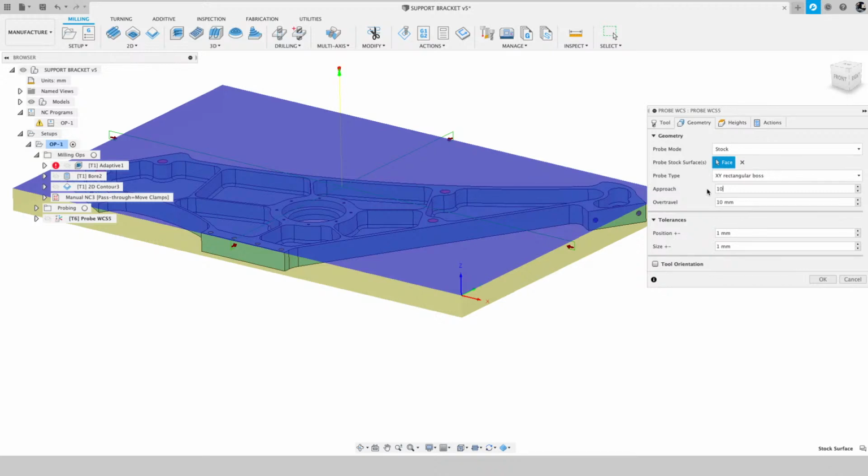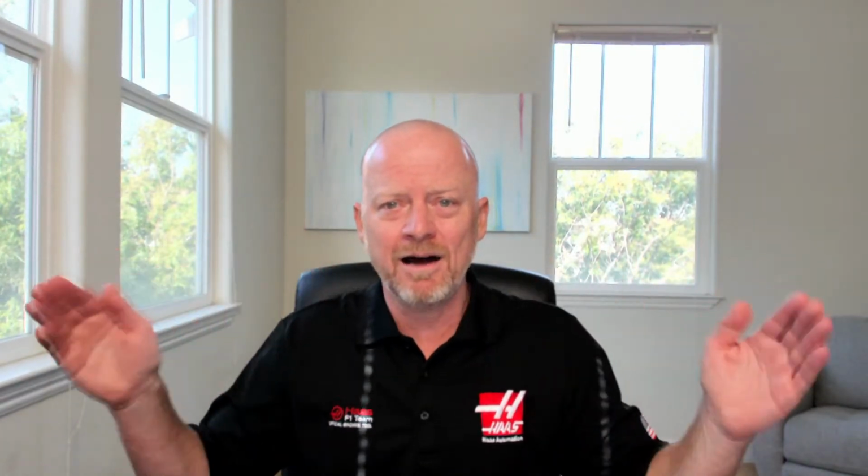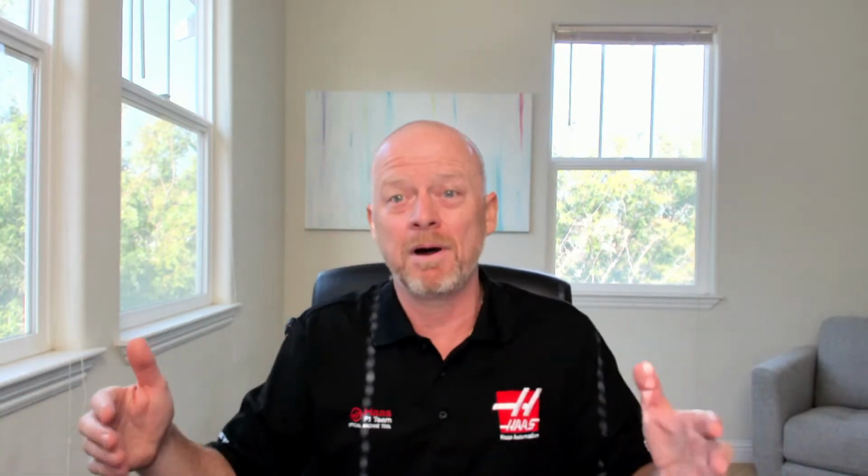Obviously, the bigger the distance, the longer the cycle time is going to be, and if you're doing a lot of parts, you want to save time. So you want to keep it big enough so that when the probe comes down, it's not going to collide with the top. Let's say your operator puts the part down on the table and shifts it over to the left or to the right some amount. You want to be mindful of that and give it enough clearance so that the probe can come down and hit the part.